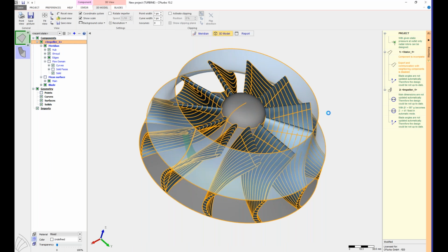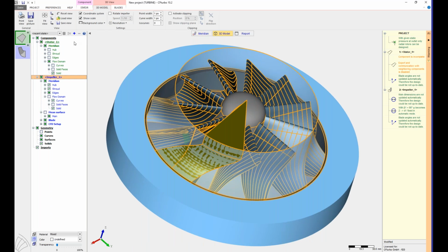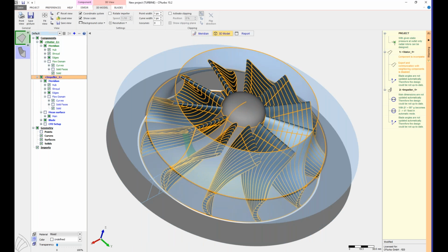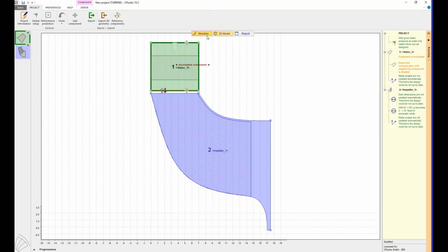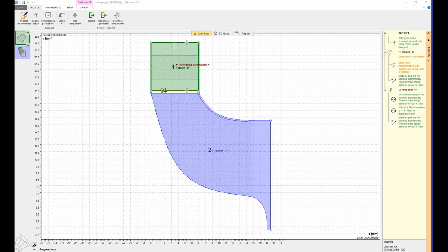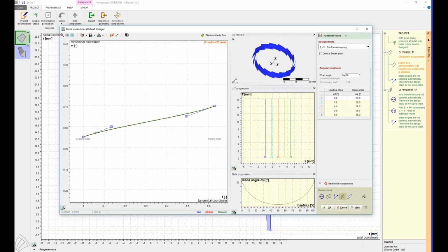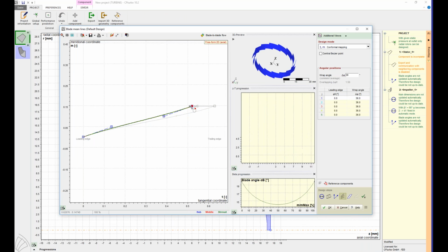Okay, in 3D we have now something like that without nozzle vanes, because I'm at a state where only the blade angles of the nozzle vanes are defined. That's why the next step is again the mean surface design step, where I can only adjust one, what we call mean line, because of that blade shape which is freeform 2D.